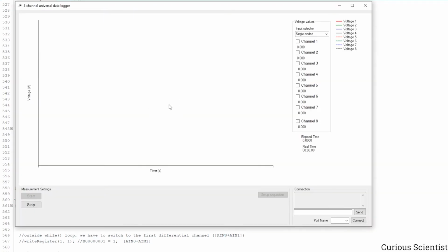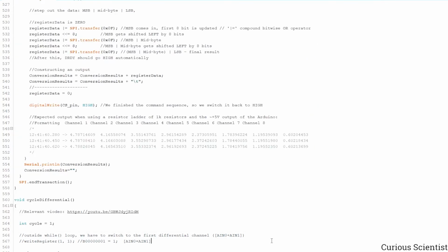So I wrote this software in a way that it is mainly controlling the ADS1256, but it's not a problem if you don't have it, because you can also just use it to capture the data from the AD converter of your Arduino or STM32 or whatever device that can connect to the COM port, like here, and can send the numbers in such a format.